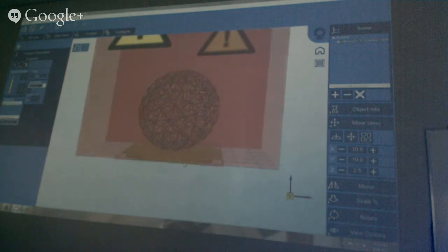So for this layer, usually we just click it and drop it lower. So three quarters of it will stick below Z0. When you slice it, it won't give you any layers. It will slice from Z0, so the effective thickness will be 0.25 millimeters. So just remember to use that in Creation Workshop.